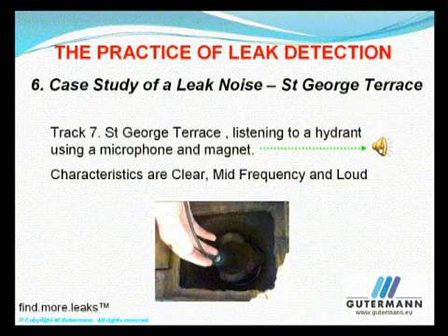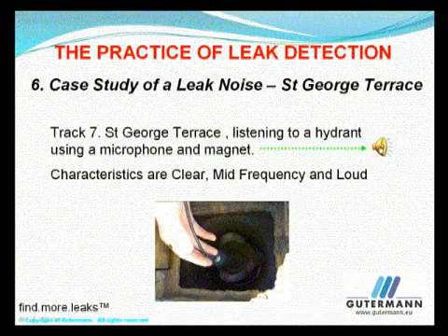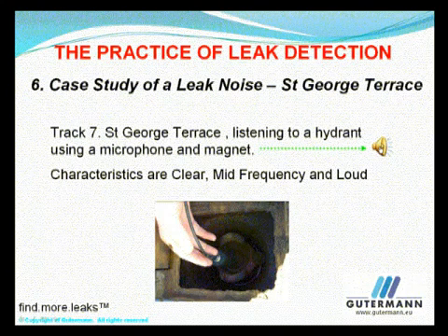In this track, you hear the same leak as in the previous track. However, the sound was recorded from a ball hydrant. You can hear there is a big increase in the amount of low-frequency background noise.